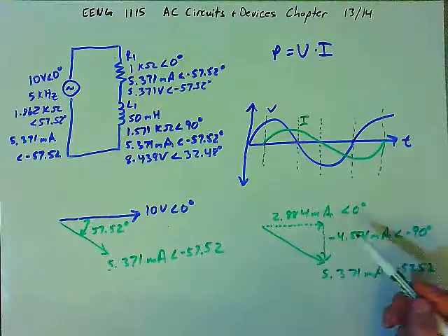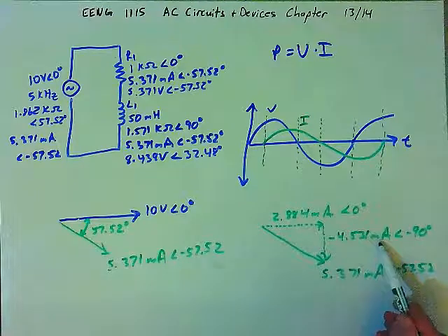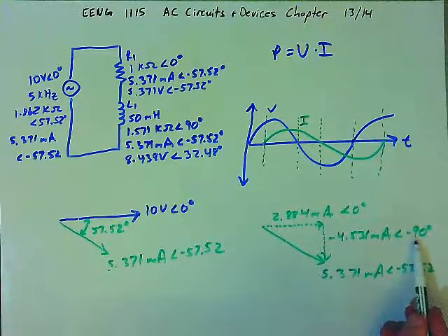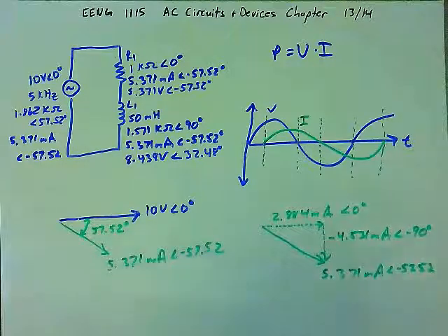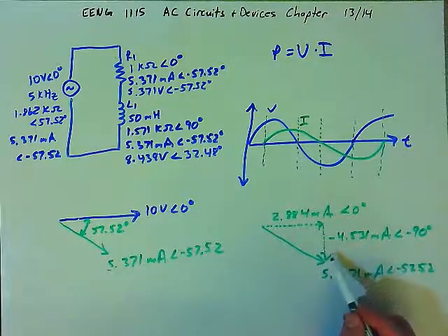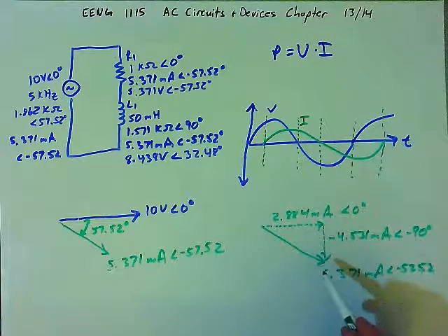And if we were to multiply the y component of this vector times the voltage vector, and they're 90 degrees out of phase, we'll get what we call volt amps reactive, or VAR, or VARs. And that represents the imaginary component of the power.